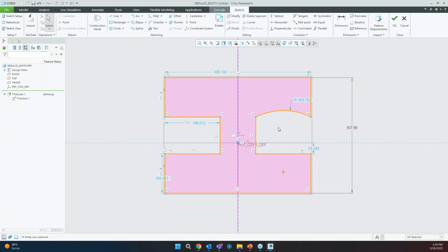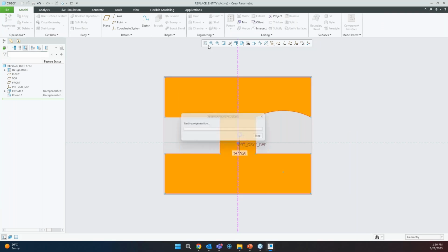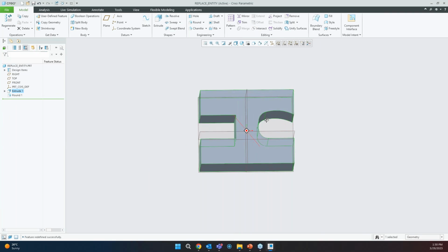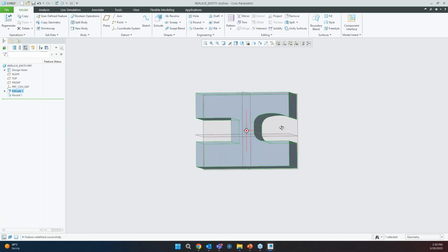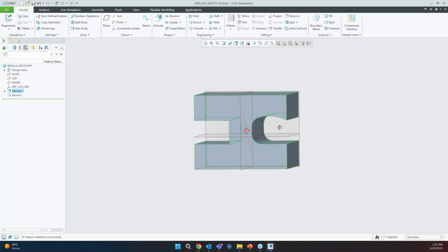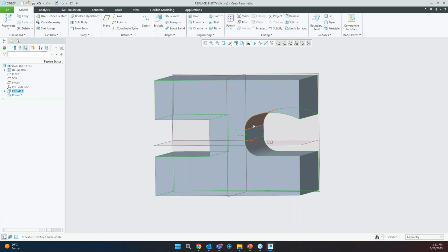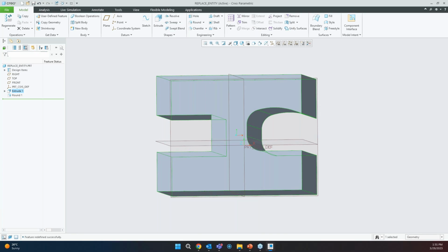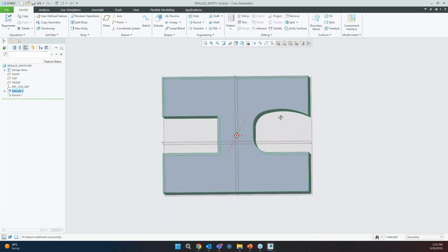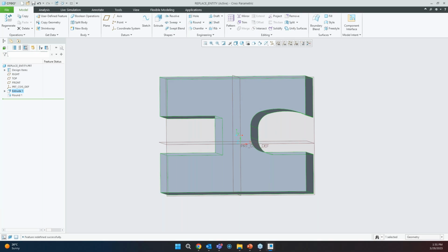So when I click on this, the references which are there for the fillet get transferred to this arc. Now, when I hit OK and then come back here, I still have this arc here, and then I've added this arc here. So this way I can go ahead and do those changes to the design a bit more fluidly without worrying about what it's referencing. Even though it's referencing something, we can just replace it with the arc, and then the reference changes to that arc as well. So this is a quick thing which I actually wanted to show.